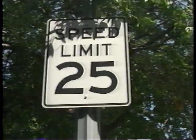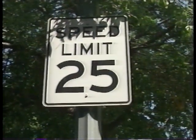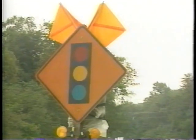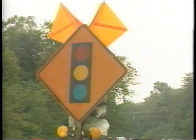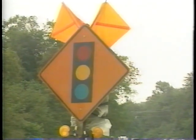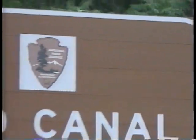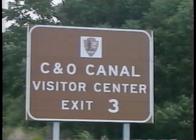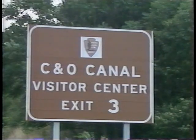Black on white is for regulatory signs such as one-way, keep right, and speed limit. Orange is used in construction and maintenance work zones. And brown is used only in the U.S. for recreational and cultural facility signs.